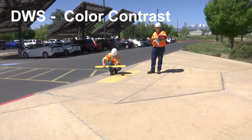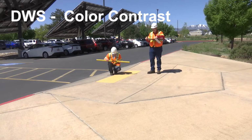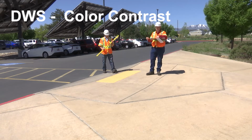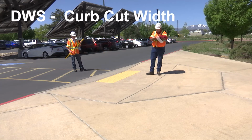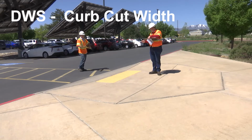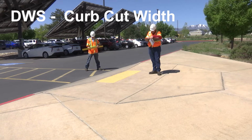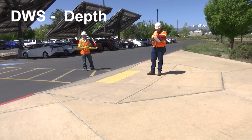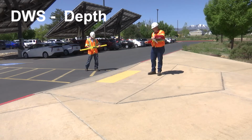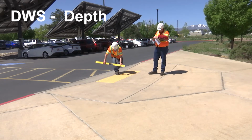Next we look to see if the color contrasts with the surrounding environment. The yellow contrasts with the concrete, so we will circle yes. Next we have the curb cut width. We just measured that, and that was 8 feet. So we are greater than the 4 feet because we only serve one direction. We pass there and we can put a little note of 8 feet wide. Next is the detectable warning surface depth. That is 2 feet.